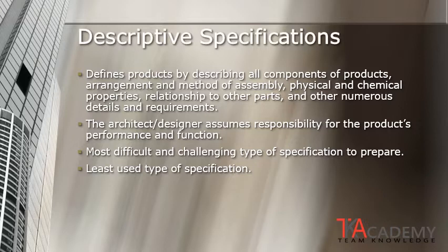In the case of many model specifications, where one is working with a guide spec that is all inclusive and it is edited by removing content that is not applicable, when there is certain content that the editor is not sure of, what is intended or if it's required, it's always best to not include that in your specification because of the open liability that the designer may carry for requiring something in the project that the editor is not sure of.